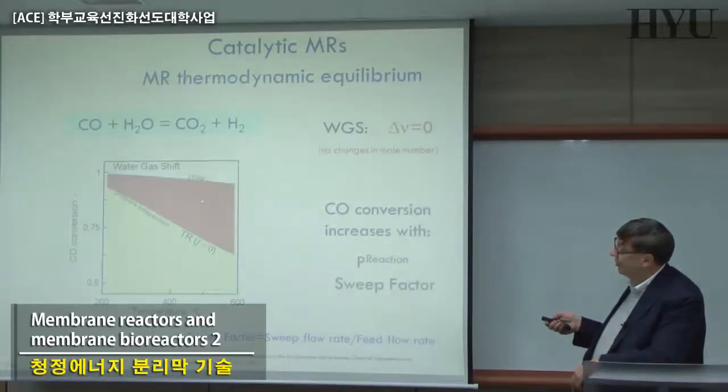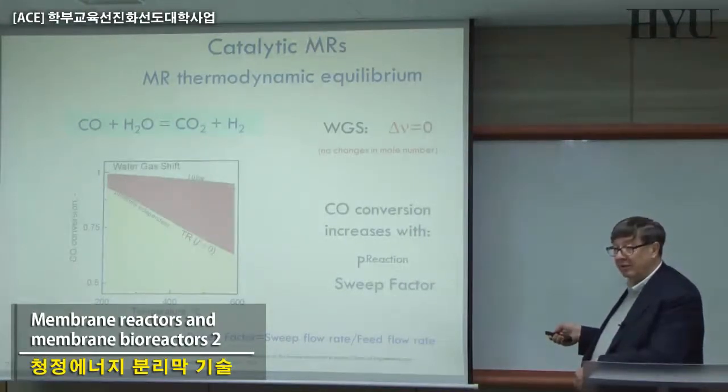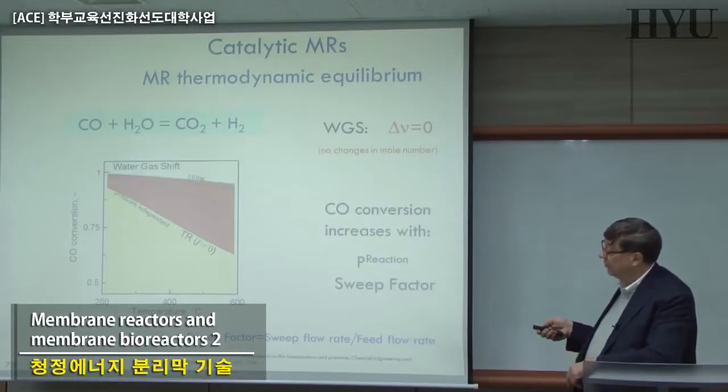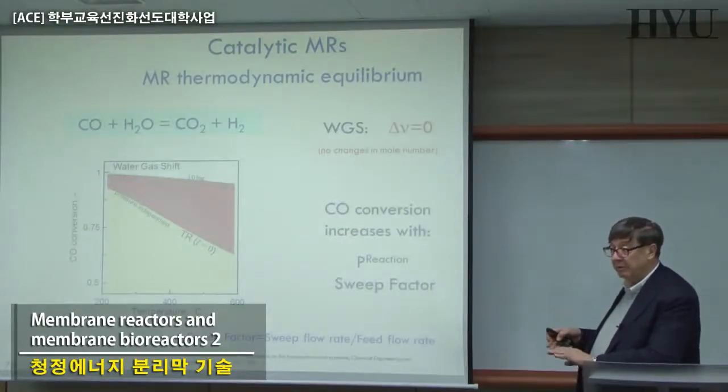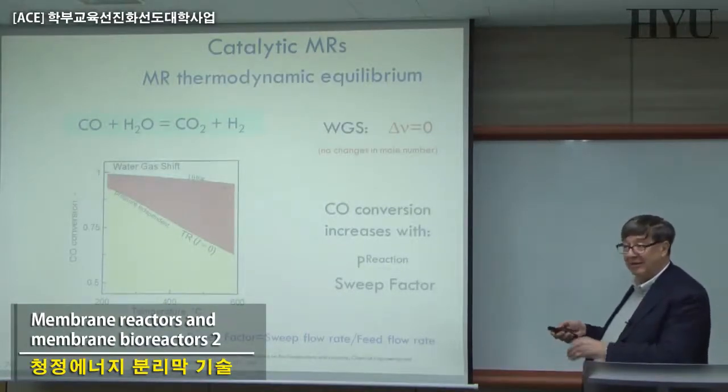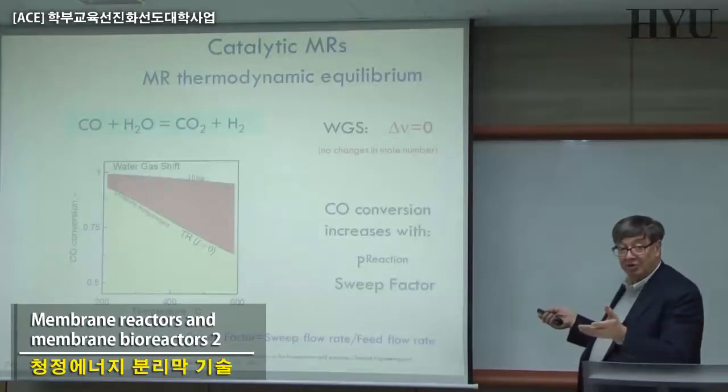But what is also interesting is that if you change the pressure from 1 bar, the same down here, to 5 bar, 10 bar, you will see that the CO conversion increases with the sweep factor. So if you have a difference in pressure across your membranes that you can realize, for example, by having a sweep factor, we can still improve the productivity of the system by applying pressure. That is something the Le Chatelier principle, the basic principle that characterizes any chemical conversion, was not suggesting.